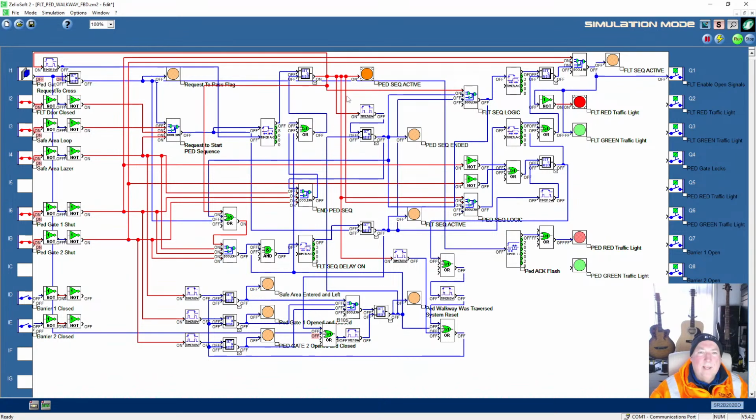Right, as soon as that becomes active, yeah, active, but it hasn't released, hasn't done anything, but we need to look at these two. So their gates don't need to be shut for it to come active, but they need to be shut for the forklift truck sequence to become active. Now these need to be down before it will release. Yeah, can't switch the traffic light mode over till these are done.